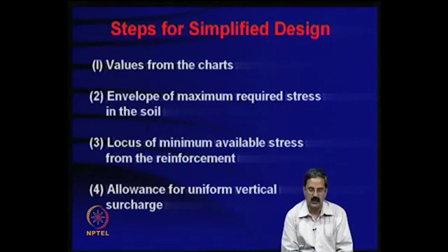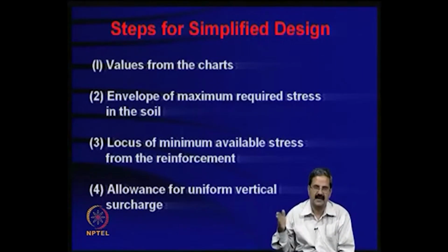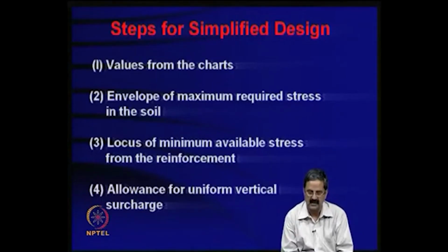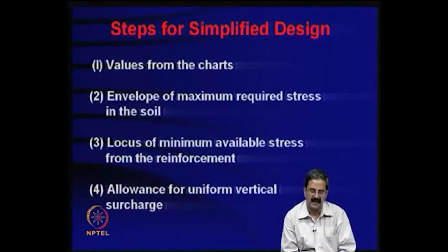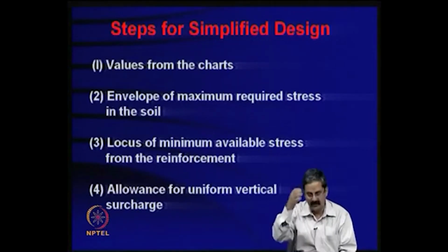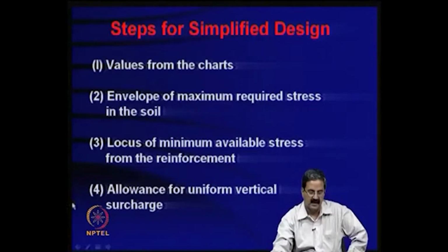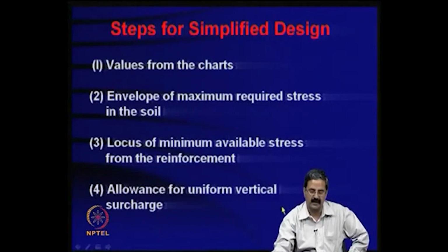You know something is required: the earth pressure at any point is calculated in terms of Ka gamma h. But what is it that the reinforcement can give? If it is very stiff reinforcement, it can give inward shear stresses, and it can be a little stiffer. So that is what is available, and there is also a surcharge and other things, and one can consider some of these things in some designs.